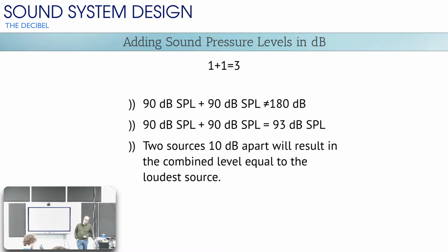Well, there's a lot of folks out there that will spend a lot of time figuring this out, and you might have seen this if you've ever been to live concerts, where they've got rows of subs across the front of the stage, all spaced apart. They're not touching each other; they're actually spaced apart. Why are they spaced apart? Because they are trying to create a directional sub bass. They're purposely spacing these apart in such a way to create a cancellation on this axis for the subwoofers, so that they will stay off the stage.